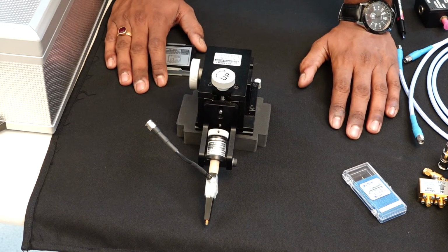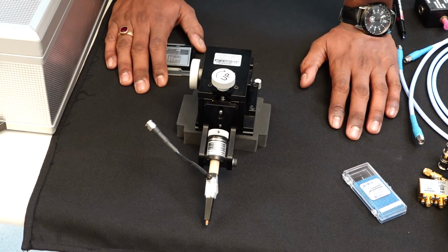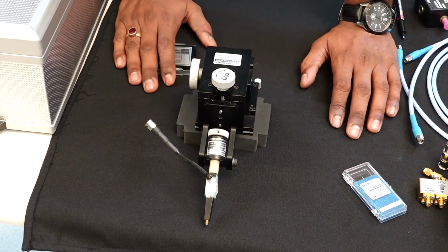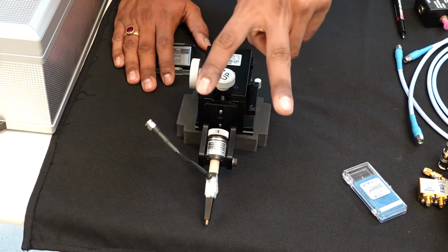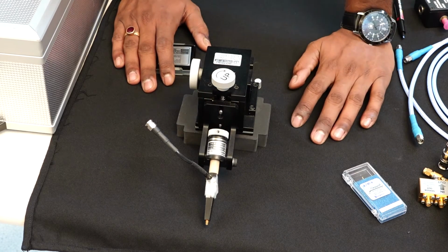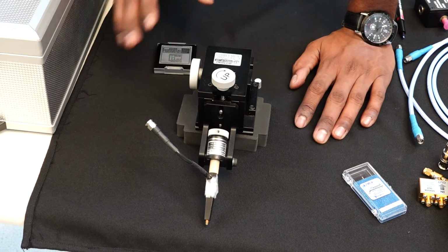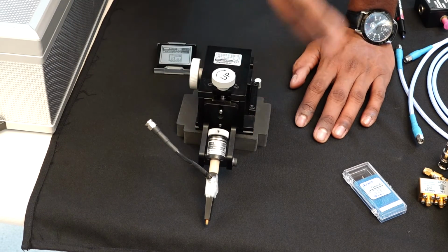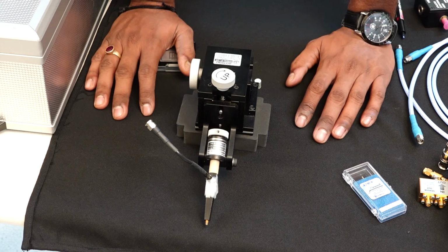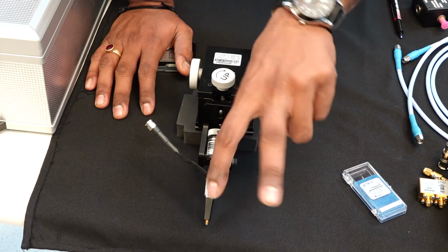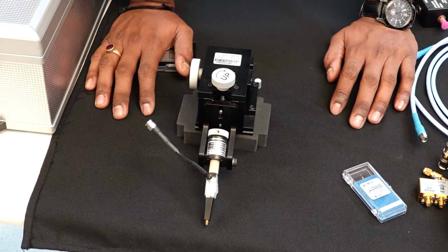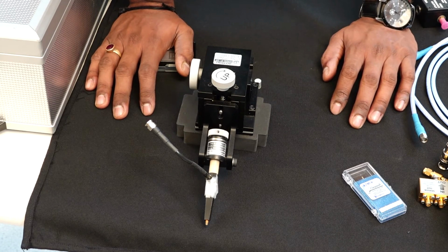Another important thing that we have in our probe arms is, when you're doing a TLP measurement, as I told you, the probe wires of the probe tips are also connected to each other. When you're doing a measurement, it's important that those probe wires are in the same plane, or at least in the same plane as the contacts that they're going to make contact with. If your probe wires are in different planes, you would not be able to make contact with the device easily, because one of your probe wires would be touching the device and the other would not be. So it's important to bring them into the planes that you want them to be in.